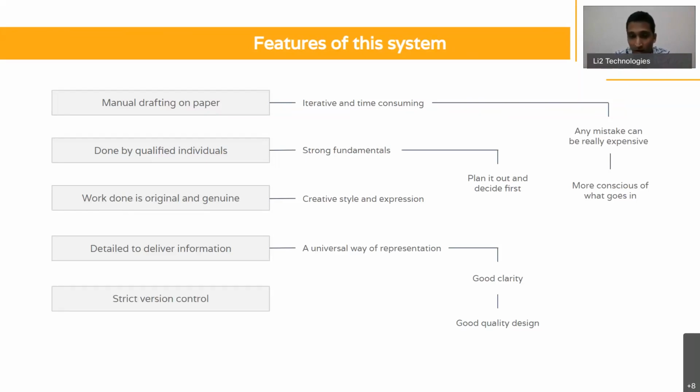There was a strict version control. At any time anyone would make a change, they had to write down what change they were making and where they were making changes. So quite often they would represent it by alphabets whenever they make a change, and they would mention the zone in the drawing where they made a change. So people, when they saw the tab where the version control was, they could directly go to that area and understand, okay, this is the change. So if this person is making this change, and since my component is part of this, I'll have to make a change in my drawing too. So people would maintain version controls earlier.